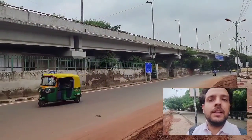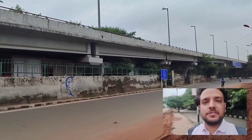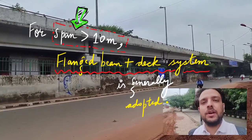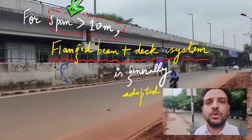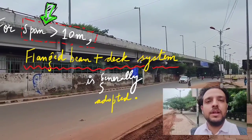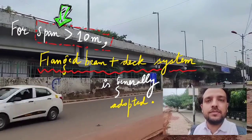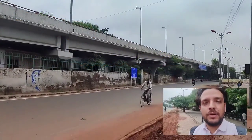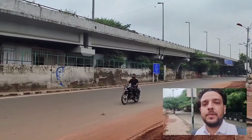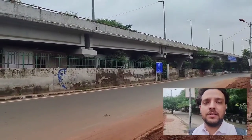If you plan a solid deck slab above 10 meters of span, its depth will be around 1 meter, and for any carriageway you will notice that the total volume of concrete in a solid deck slab will be way more than in a girder plus deck slab system. That is one reason why flanged beams are generally adopted for structures spanning above 10 meters up to 25 to 30 meters.